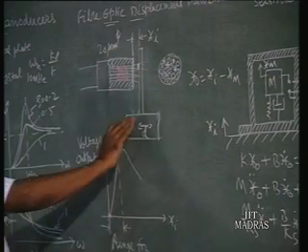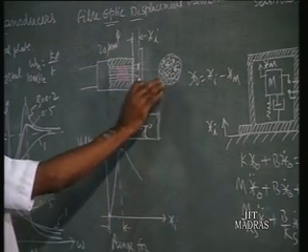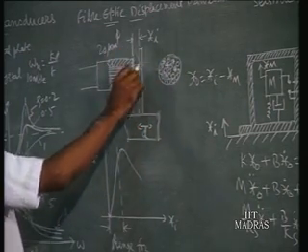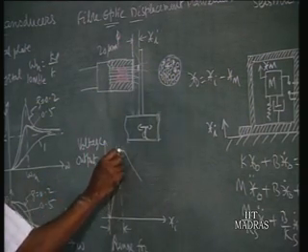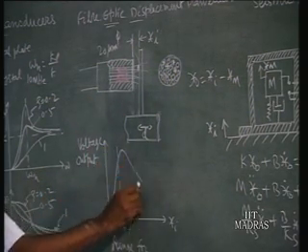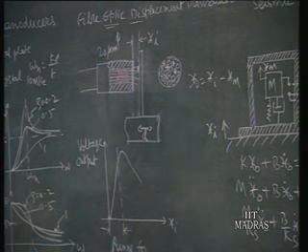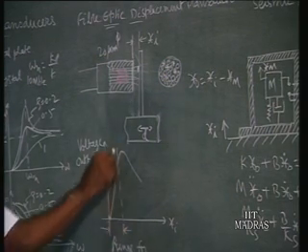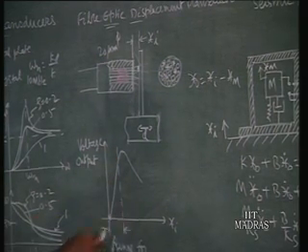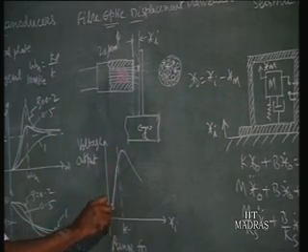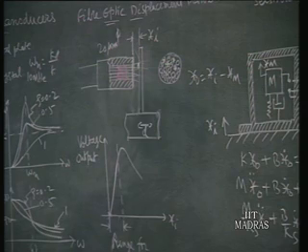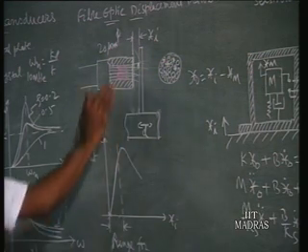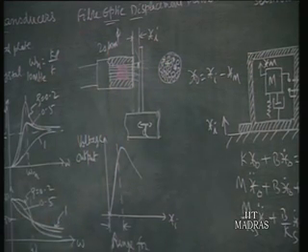But that is only up to a particular distance. Later on, the light lost to the atmosphere becomes more and more, and you will find the voltage output of the instrument starts drooping down. So for a particular distance we can measure; that is the linear range in which the instrument can be made use of, say from 0 to 1 mm or 0 to 4 mm. Up to 4 mm such fiber optic displacement transducers are available.